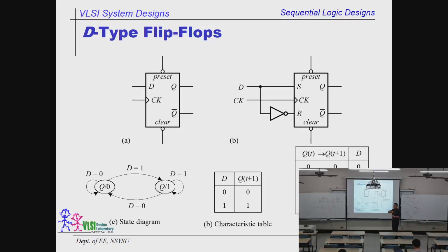Because when the system is powered up, you don't know the original state of the flip-flops after power up. You got to make sure that all the flip-flops will enter a predefined state after you turn it on. So we got to remember this one.